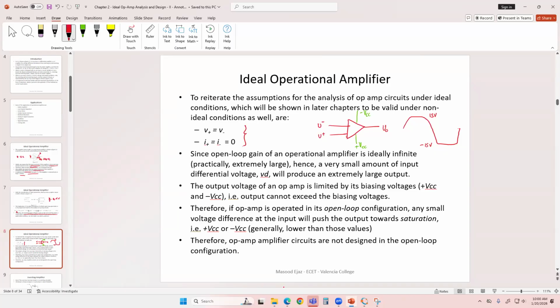should be, since the output voltage exceeds 30 volt peak to peak, the output voltage is going to be the maximum value, that is 15 volt on the positive side and negative 15 on the negative side. It's going to just clip at that value. It's not going to be 41 volt in the practical circuit. Of course, in the quiz, we say 41 volt. That's fine, because we did not mention any saturation or anything at that time.